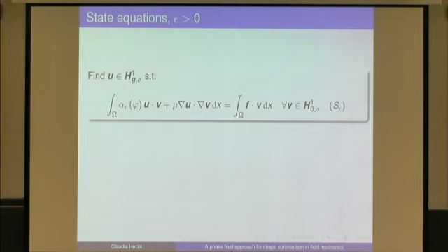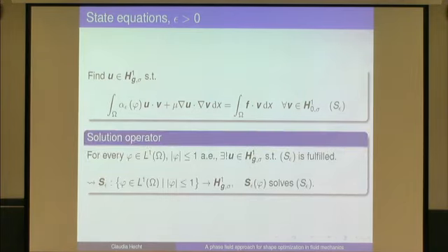Now this equation can be understood as follows. If you're inside your fluid region, phi is 1, then this term vanishes and you just have your Stokes equations. And if you're outside the fluid region, then alpha epsilon is again constant but has a very high value. And then this equation describes fluid motion through a porous medium. So here we have this porous medium appearing, and so we somehow relax the condition of non-permeability outside the fluid region. We have now a porous medium with small permeability.